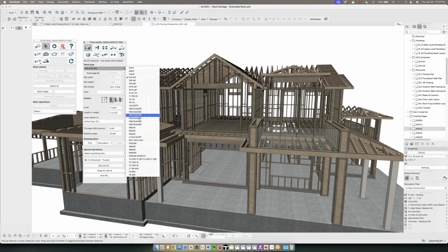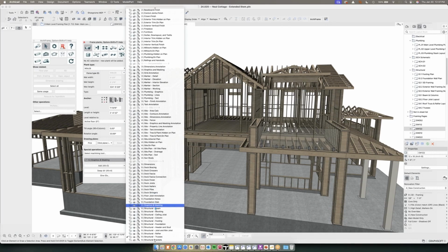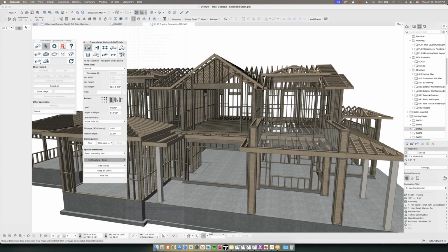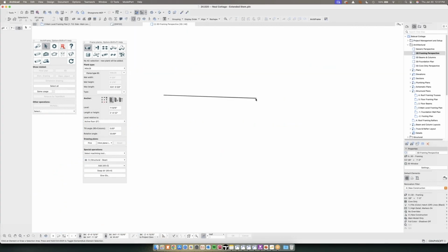In terms of placing an element, it's really a matter of grabbing a beam. For example, if I want to place a steel beam, I could grab a W8x28 and change the layer that I want to put that beam on. And simply, if I wanted to add that element in 3D, I can add that element in 3D. Now all of a sudden, I'll put it way too far away, but that element is now a W8x28 steel beam added in 3D.